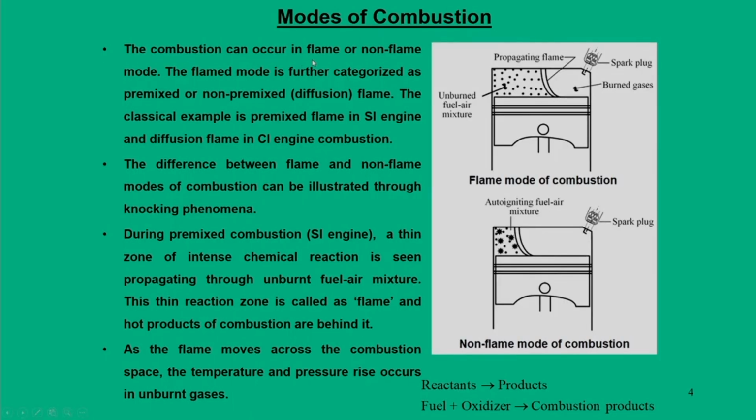And in a compression ignition engine, the fuel and air are separate entities, and they mix as and when they meet or are admitted at some interface in the combustion chamber. So this is the very basic difference that makes the nature of the flame. So the combustion can occur in 2 types of modes. One is flame mode, other is non-flame mode. Typically SI and CI engines are flame mode. So the flame mode is further categorized as premixed or non-premixed.